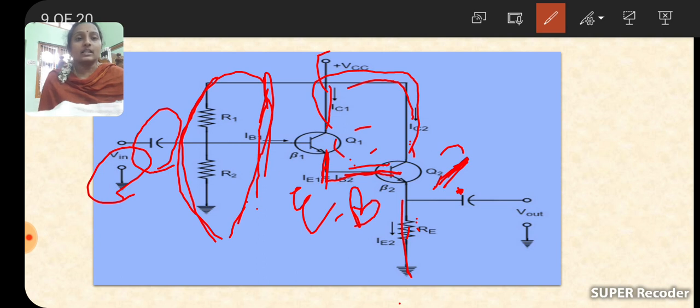If it makes the operating point independent of temperature variations, what is the advantage to us? It provides constant gain. Otherwise, with temperature, the leakage currents will increase. Due to that, the current gain increases again and again. Finally, self-destruction of the transistors occurs, and the transistors will be damaged. That problem is called thermal runaway.